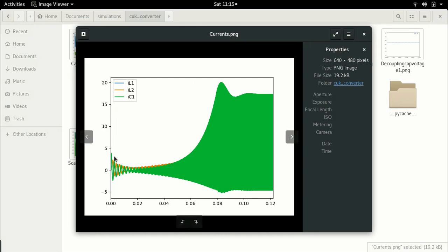And the reason for there not being a huge spike in the current is because we are starting with almost 0 duty ratio, which means initially the switch is turned on for a very short period of time. And because the switch is turned on for a very short period of time in the beginning, there is no spike in the current. Because remember, when the capacitor is uncharged in the beginning, if you turn on the switch for a significant amount of time, you will see a huge spike. So therefore, this is almost some kind of a soft start, right? So you see the current is increasing.